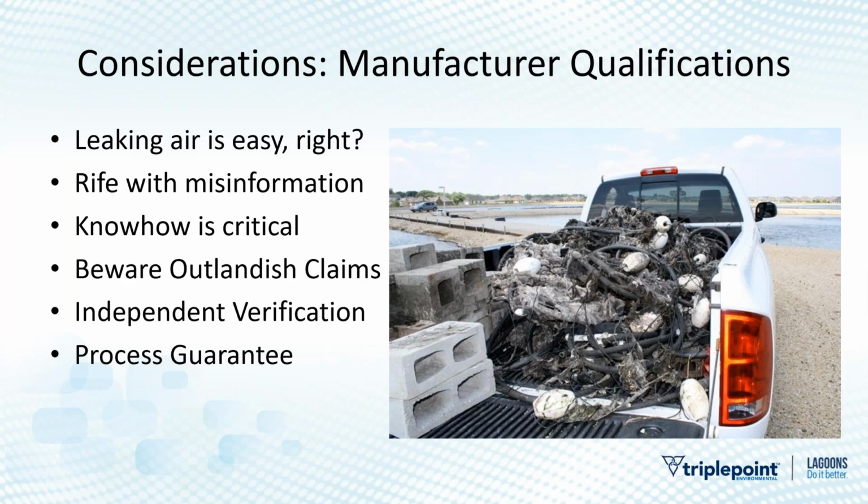Similarly, this is an aeration system that we actually ended up replacing in 2009. Same kind of deal. They took soaker hose and coiled it up into a pretzel, and it didn't last. It's technology that's not proven over time. It wasn't independently tested. The pond had DO issues, and the aeration system they put in about 10 years prior, they paid all that money for, they had to rip out and start all over again. But yeah, this is just soaker hose tied to cinder blocks. So make sure you're not getting soaker hose tied to cinder blocks.